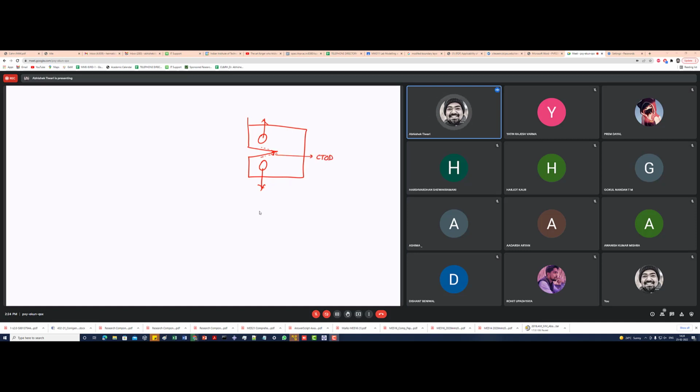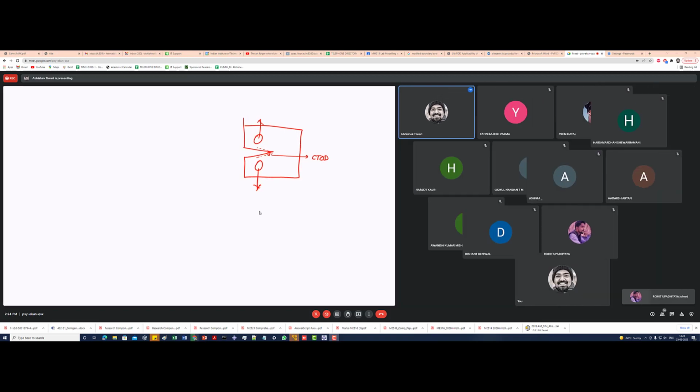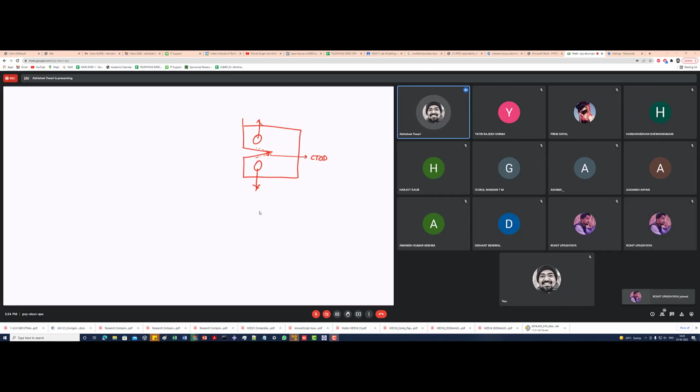There are various ways of measuring how much the crack is opening, and from that you find all the different parameters which define the material's resistance towards cracking. But you cannot find out the strain, and also the stresses, by experiment at the crack tip while the test is going on. So one way of doing this is by finite element simulation.